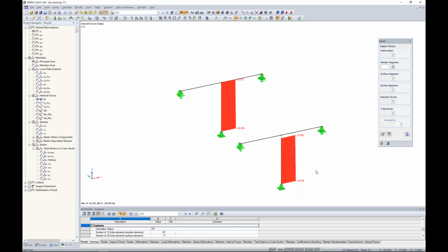so 0.04 kips of difference. So my point being here is that we perhaps have a huge model. We've gone through, we've applied all these eccentricities for our columns to drop that down to the bottom of the beams framing up above it, with absolutely no influence or very, very little influence on our results that really don't make it worthwhile. So maybe not detrimental here in terms of additional forces, but really no difference. So there's no reason to apply these offsets in these situations.